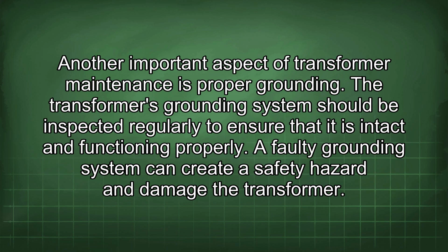Another important aspect of transformer maintenance is proper grounding. The transformer's grounding system should be inspected regularly to ensure that it is intact and functioning properly. A faulty grounding system can create a safety hazard and damage the transformer.